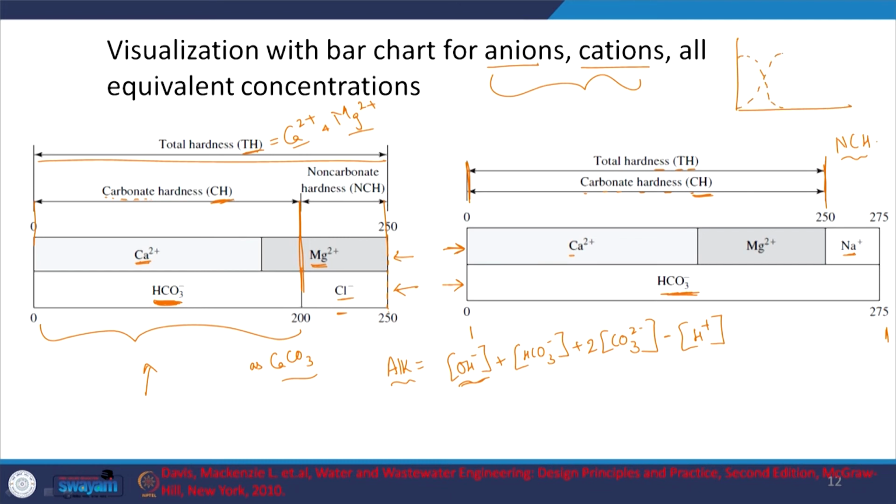But knowing that your particular system is a carbonate alkalinity system, I think we discussed this earlier, it is going to be something like this. This is H2CO3, this is HCO3 minus and this is CO3 2 minus. As you can see, at around pH 7, as I told you, pKa is 6.3, and near the neutral pH of water, which is pH 7, CO3 2 minus is almost 0, and at pH 7 OH minus and H plus cancel out.